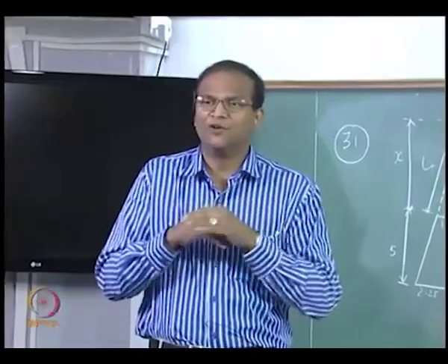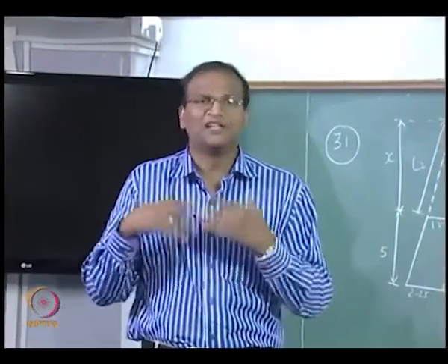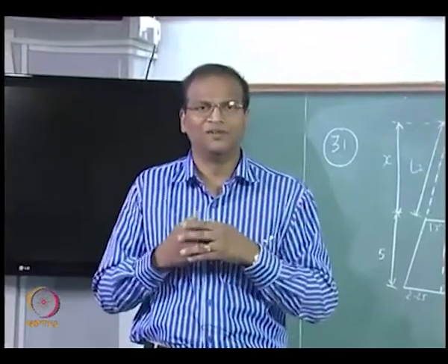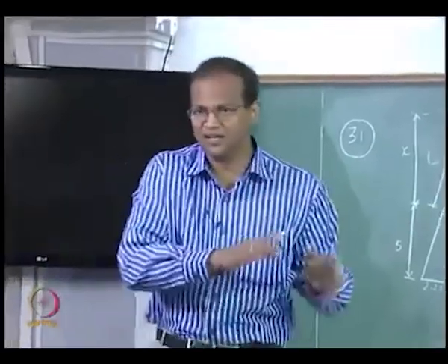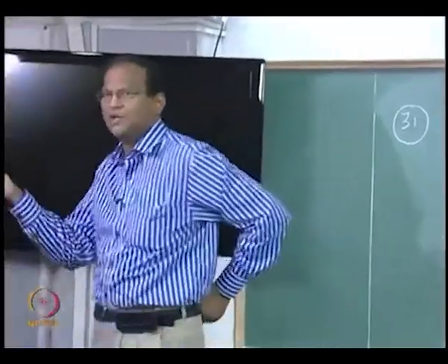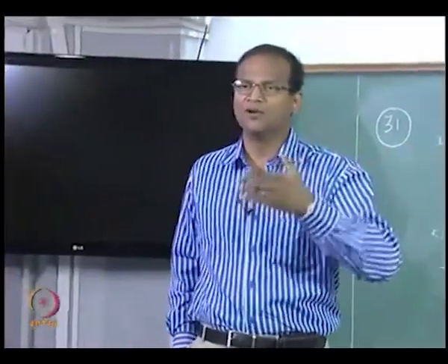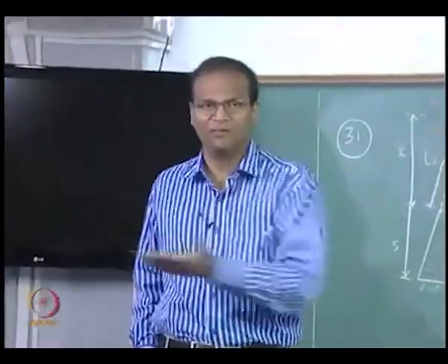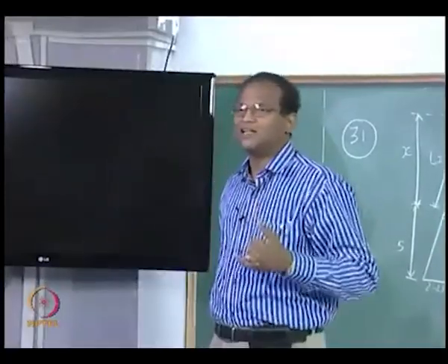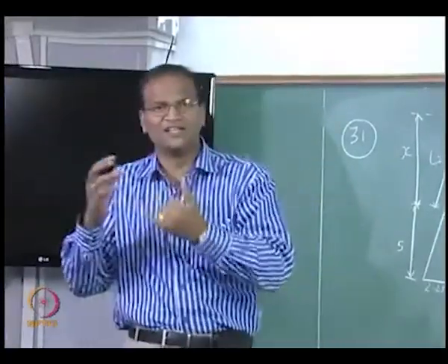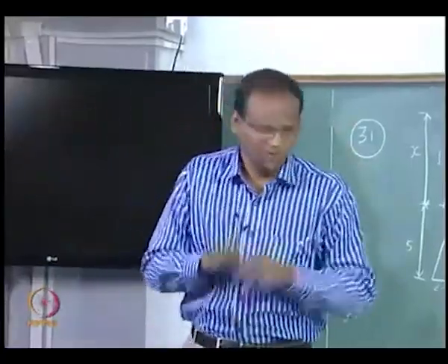And the radiation, people normally do not update radiation in every iteration, because radiation is well behaved compared to convection. So once in 10 or 20 iterations of convection we will stop and do the radiation calculations and then proceed. Even though it is T to the power of 4, you think it is non-linear, the convection is u dou T by dou x or u dou e by dou x, which is terribly non-linear compared to this, okay, the convection, the advection, because it is very direction dependent. If it is a recirculating flow, if the direction changes, then the u, v, all that will struggle to converge, okay. So we will stop.